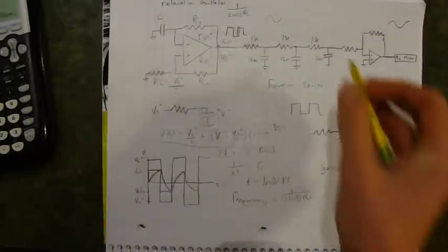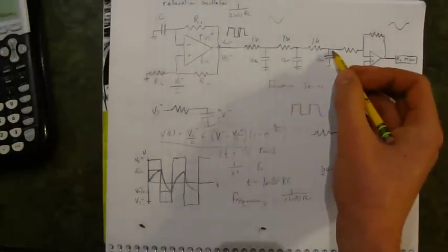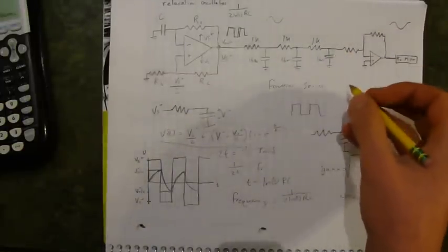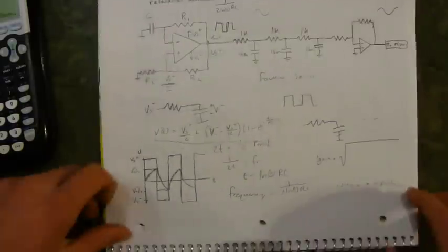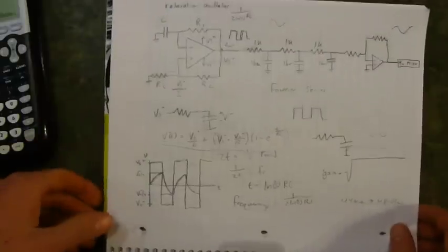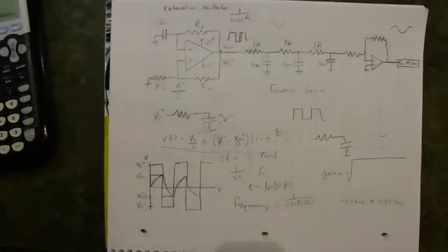But by the time the sine wave gets to the mixer, it's been attenuated considerably, because the gain, even at 48 kilohertz, is still, what was it, like 80%? I mean 0.8. Let's calculate the value at 48. Yeah, it's 78%. 0.78 is our gain.